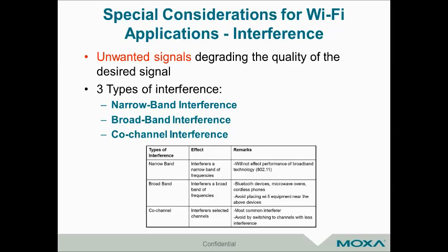The last one is a high gain or directional antenna. These look exactly like you see in the picture. They're basically flat panels, and they're typically used for point-to-point or long-distance communication, so they tend to be very high gain. In fact, they allow Wi-Fi to go upwards of 10 to 20 kilometers, which is not the distance you typically associate with Wi-Fi. But if you want to go that distance, you are going to have to look at a very high gain antenna. Again, these tend to be point-to-point, a one-to-one connection, so they're not good for many devices trying to have access. They're good for just bridging two remote locations together.